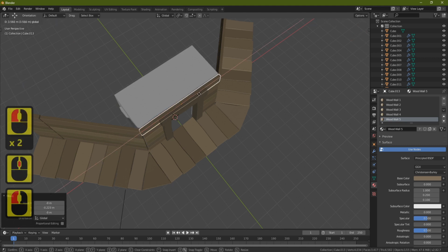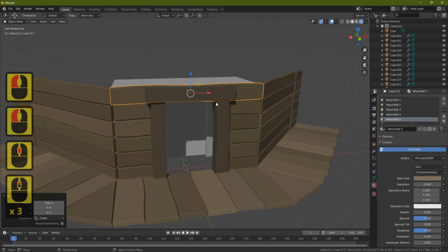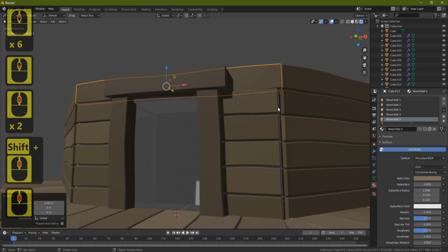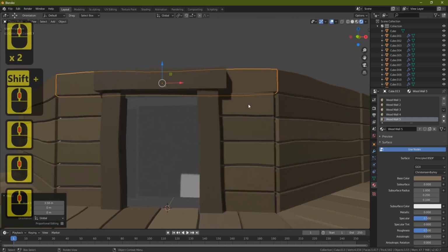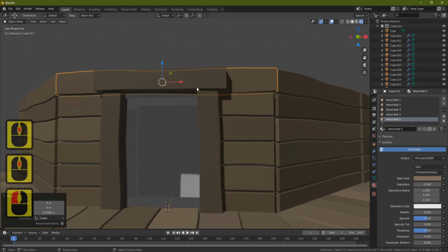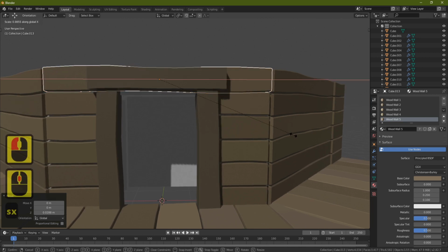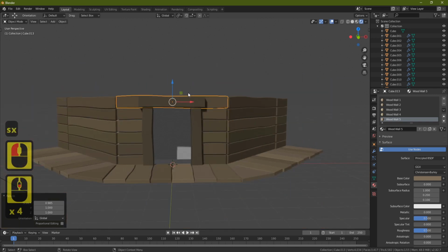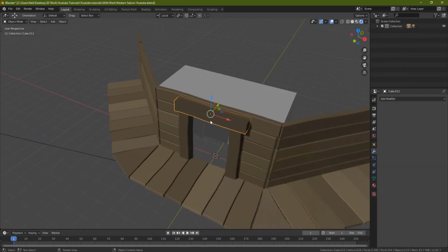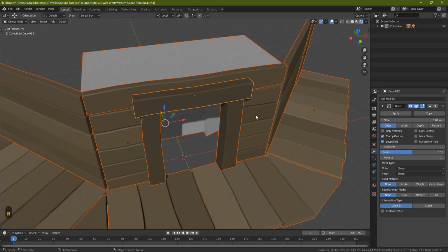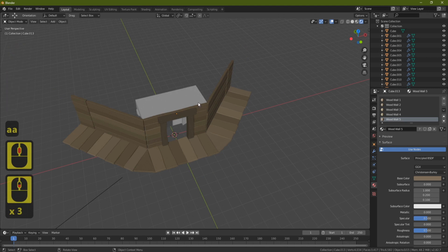And you can see now why I'm actually doing this, because it's one complete piece rather than two little pieces. And you can see that they're a tiny little bit long. There is a post that's going to be covering those as well, so we haven't got to worry about that. Let's lift it up just a tiny bit, because you can see now there's a gap between them. And let's press SX and just bring them in just very slightly. Double tap the A. And all we need to do now is just add in our bevel modifier. So let's go to bevel, turn this down to 0.2. Let's just check. Yeah, 0.2, and double tap the A. And you should end up with something like this.